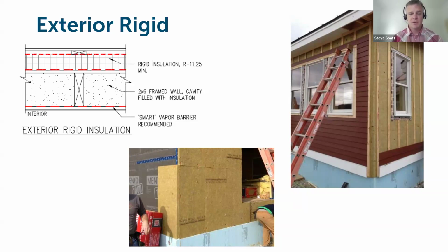That being said, from a building science standpoint, going back to the earlier slides on mitigating or eliminating the risk of condensation occurring in the assembly at that vulnerable wood sheathing layer, because that's what can be damaged and broken down if it gets wet and stays wet, the ratio is 50% of what the cavity insulation will be in the continuous layer.